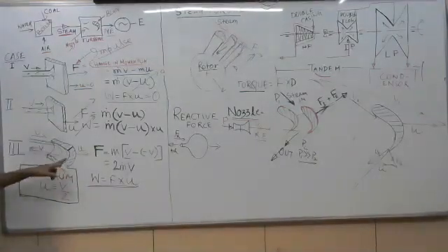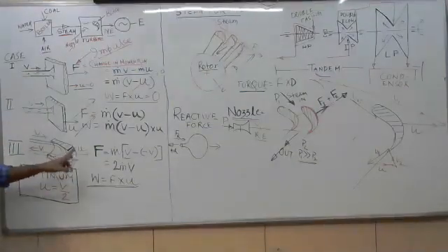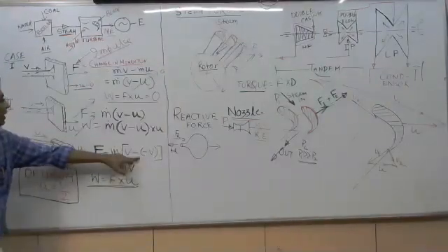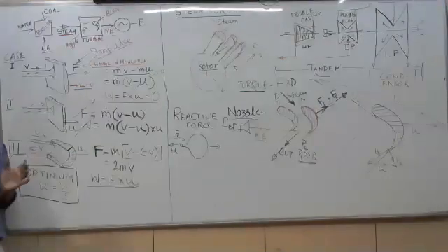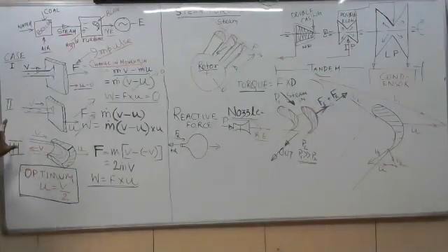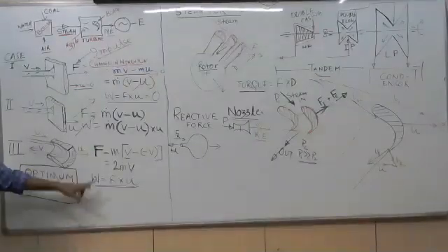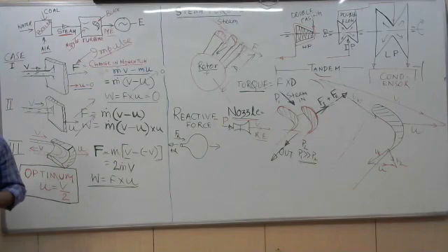How the blade can be designed comes from the third plate. We are just bending the plate to get more impulse. We are increasing the change in momentum, that is v minus (minus v), twice, by changing the configuration only. So we have to design the blade in such a way that it will give more force on it, so that more output can be obtained. That is the basic fundamental of the impulse steam turbine.